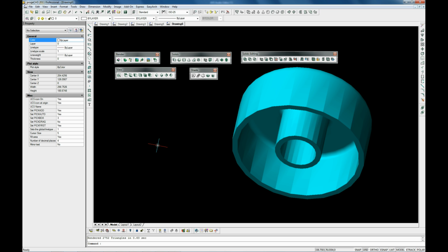Disadvantages of working with solids are that it just means a larger size, it just contains more information, so that may mean you may need better computer requirements. Some advantages, it's more professional than working with the polygon mesh. You've got curves, arcs, splines and circles. You can also create more complex models faster using the Boolean commands, and you can send to other CAD/CAM programs to be translated and manufactured.